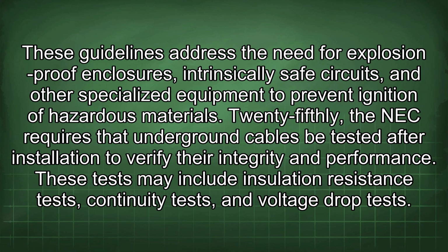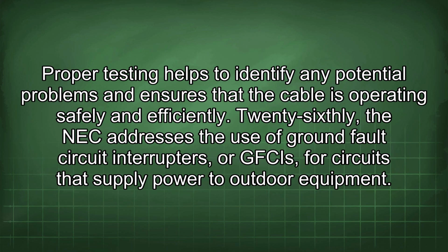25thly, the NEC requires that underground cables be tested after installation to verify their integrity and performance. These tests may include insulation resistance tests, continuity tests, and voltage drop tests. Proper testing helps to identify any potential problems and ensures that the cable is operating safely and efficiently.